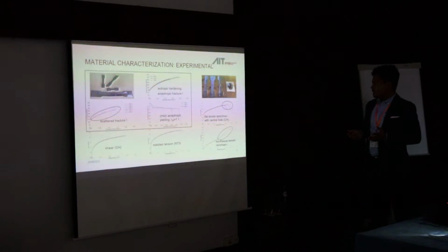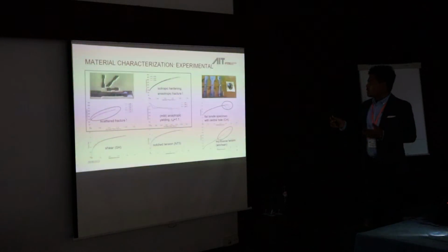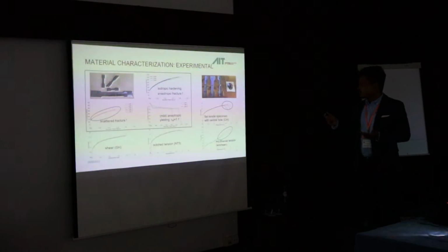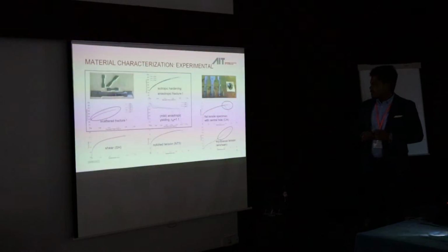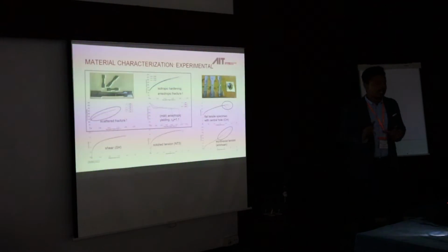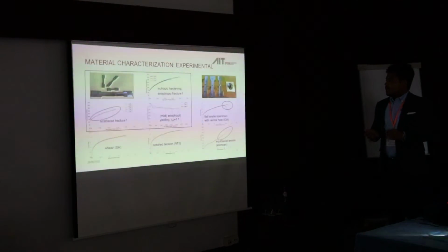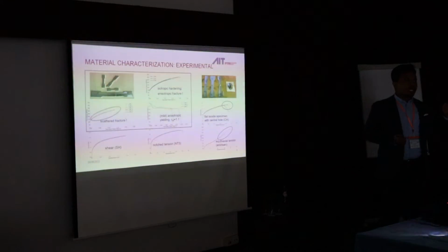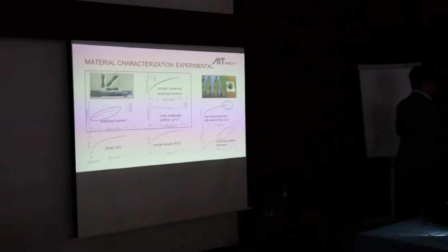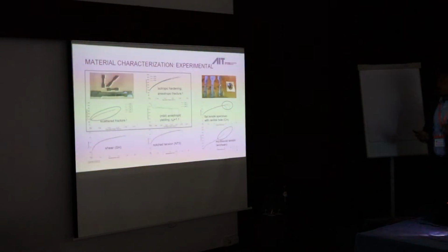What we have noticed here is, first of all, the material is quite homogeneous, so all the specimen tests gave us more or less similar force level, but we have seen some scatter in the failure again. That's also not really desirable from a numerical simulation point of view. But so now what we have: mild anisotropic yielding, indication of scattered fracture, and an indication of anisotropic fracture.